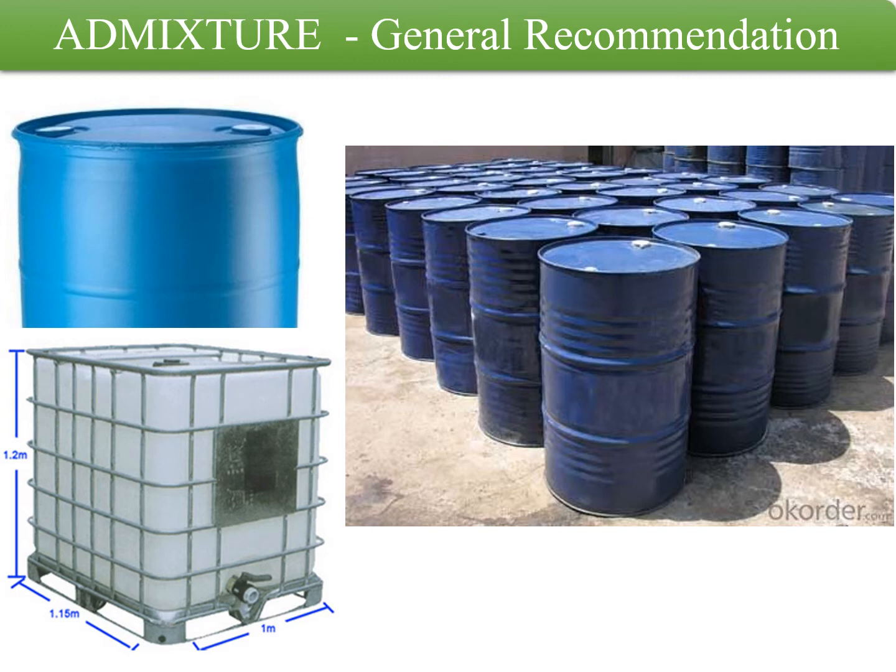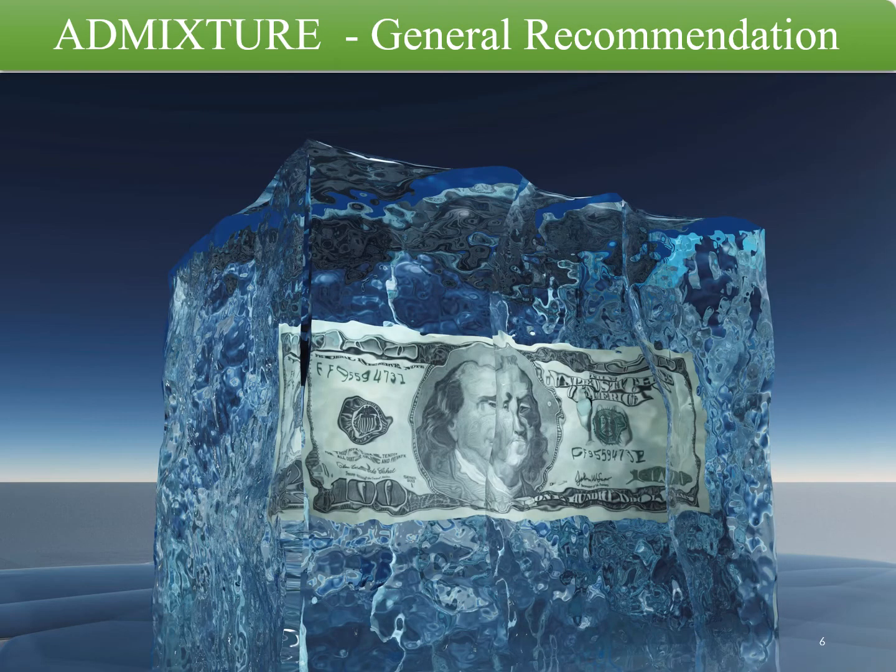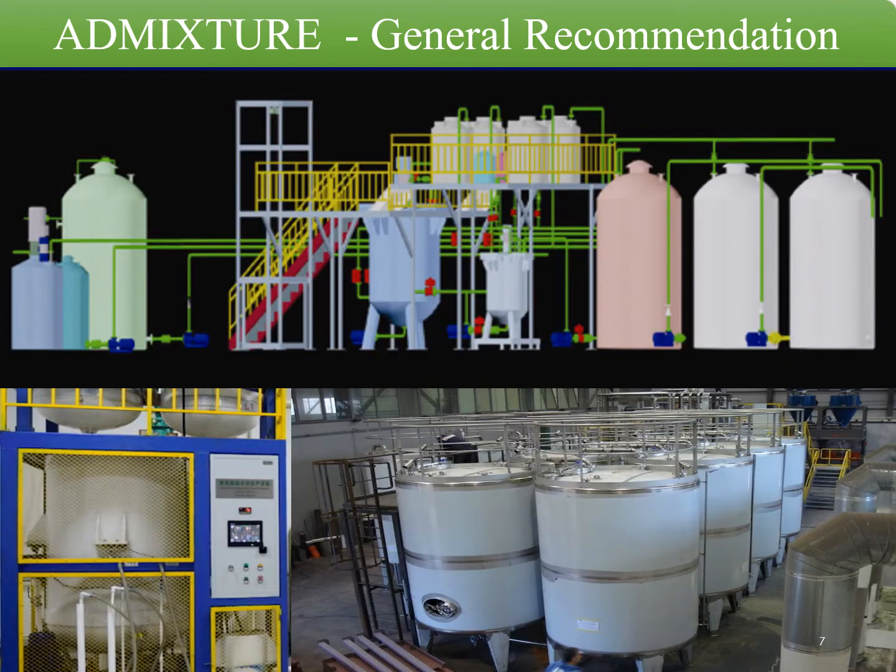Modern bulk plastic storage tanks are double skinned to minimize the risk of leakage from a skin splitting. If double skinned tanks are not used, the admixture storage areas should be bunded to prevent spillage entering the water system. Admixtures should be protected from freezing. All tanks and pipes should be clearly marked with their contents and the shelf life of the product should be indicated to have a visual impact on the users.